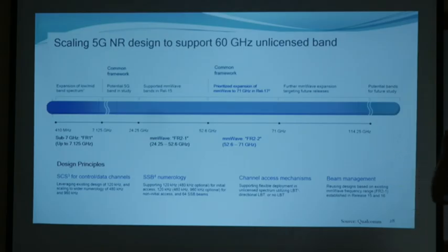In millimeter wave frequency communication, we need a large number of array antennas, like 512 antennas used nowadays, to make very, very narrow beams. And then if the user is moving, we also need to do beam tracking, etc. So these are challenges for millimeter wave communication. Blockage and all these are obstacles for millimeter wave success.